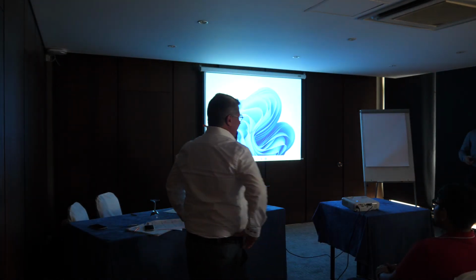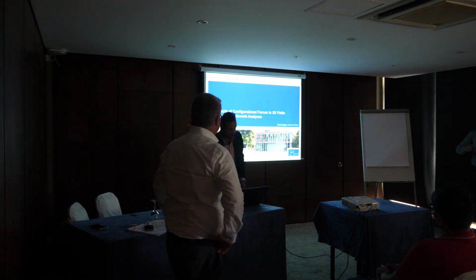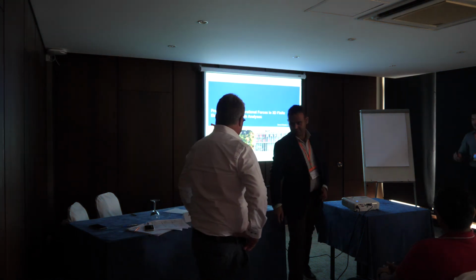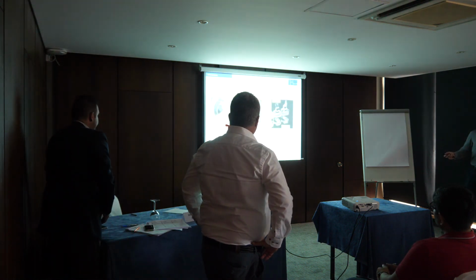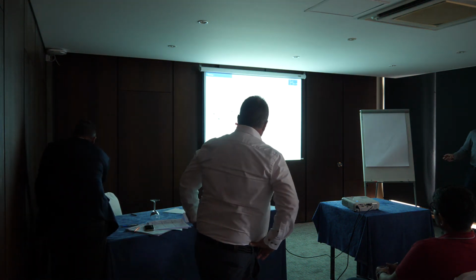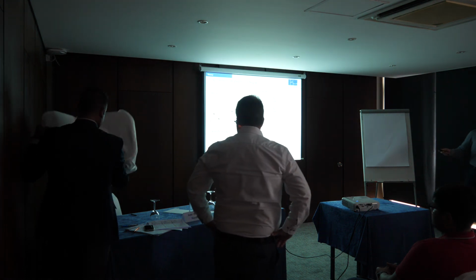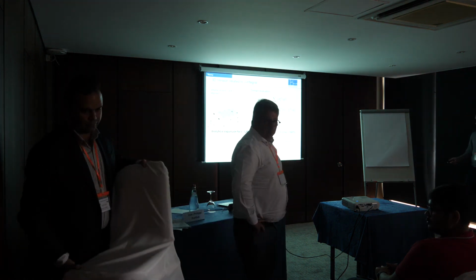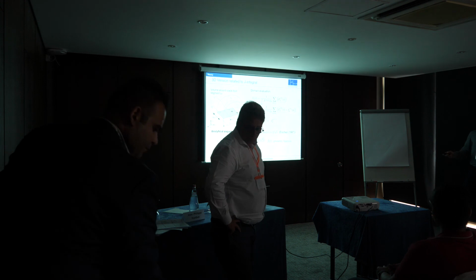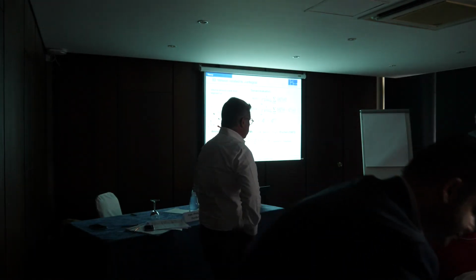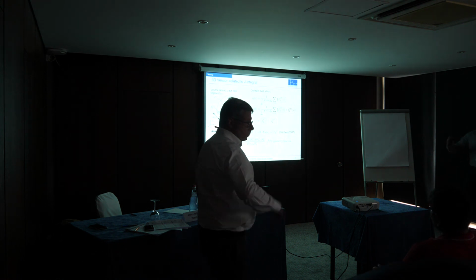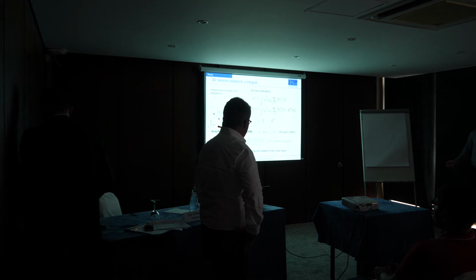The thing with the domains is they can be quite big. But if the domains get too extensive, so the two domains that we need for the extrapolation scheme, if one of these domains gets really too extensive, and I am talking about like 10-20% of the crack face being included in the domain, then the method will probably fail.